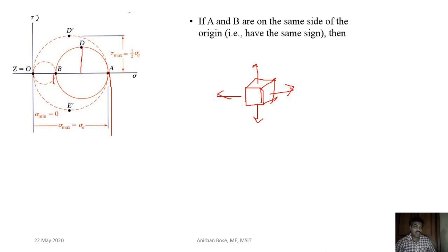Since the shear is 0, the normal stress perpendicular to the plane is 0, and that is, remember, one of the principal stresses. Now with respect to that stress, basically you are rotating in that plane. So that is why what you are getting is basically corresponding to that 0.